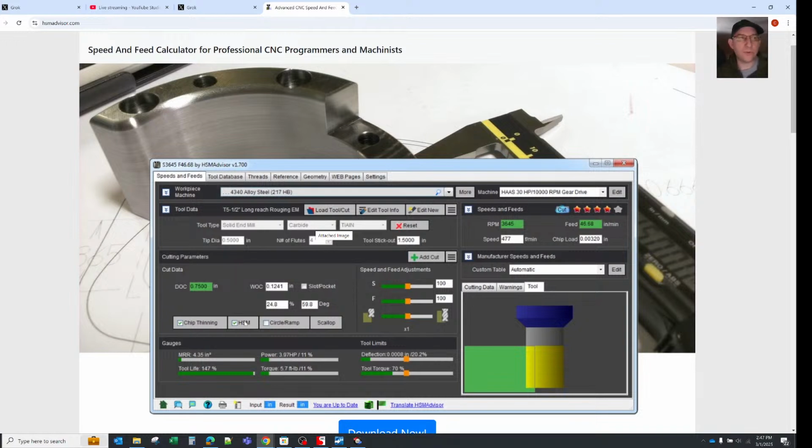You could turn on whether you're using a high-speed machining mode, which if you're a Mastercam user, that's going to be the Mastercam Dynamic toolpath. If you're using something like CAMWorks, that would be either the adaptive algorithm, or if you're in a newer one, it'll be the Volumill cycle. Fusion calls it adaptive machining. All of those things are essentially doing more or less the same thing. If you're using something like SolidCAM, their iMachining would be handling this. So all of these guys, and that takes that chip thinning into account.